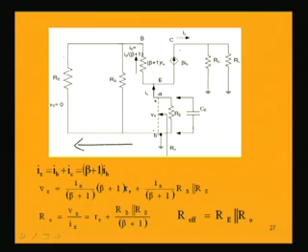This is the way to find out the output resistance, and so because of this Vx, Ix current flows and one part goes to this side which is beta times of IB, where IB is the current flowing through this resistance. Now, the total current Ix is equal to IB plus IC. IC is that current which is through the collector point, and through the base point IB current flows. So, that means Ix is equal to beta plus 1 into IB, because IC is equal to beta times of IB. So, that means we get that IB is equal to Ix by beta plus 1.